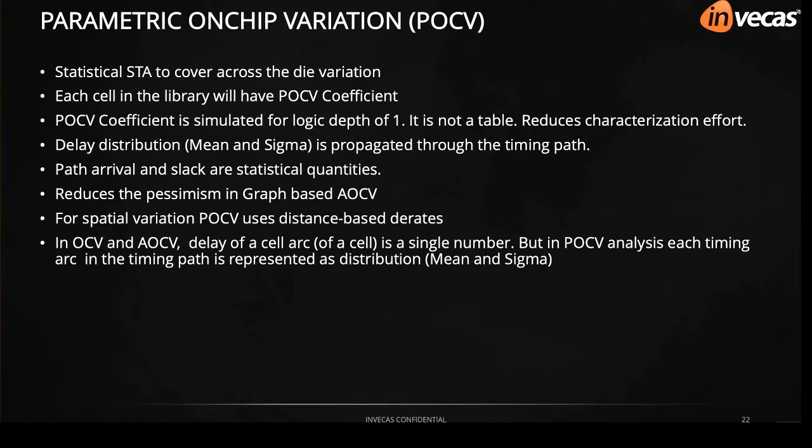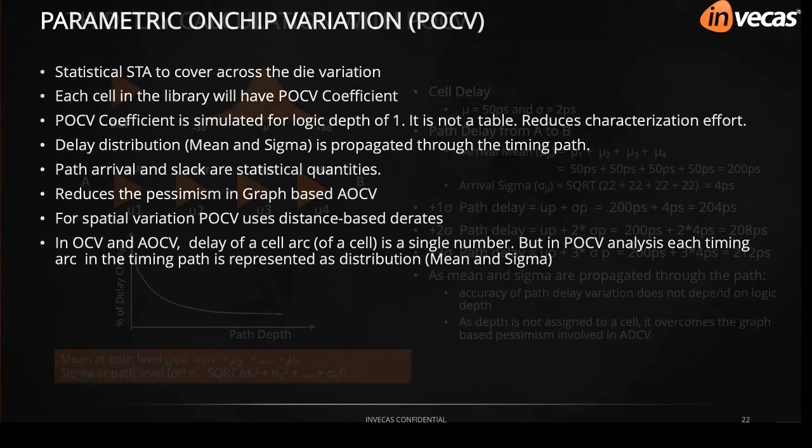POCV uses a statistical approach, but it doesn't do a full SSTA analysis. Instead, it calculates the delay variation by modeling the intrinsic cell delay and load parasitics to determine both the mean and sigma of the logic gates.